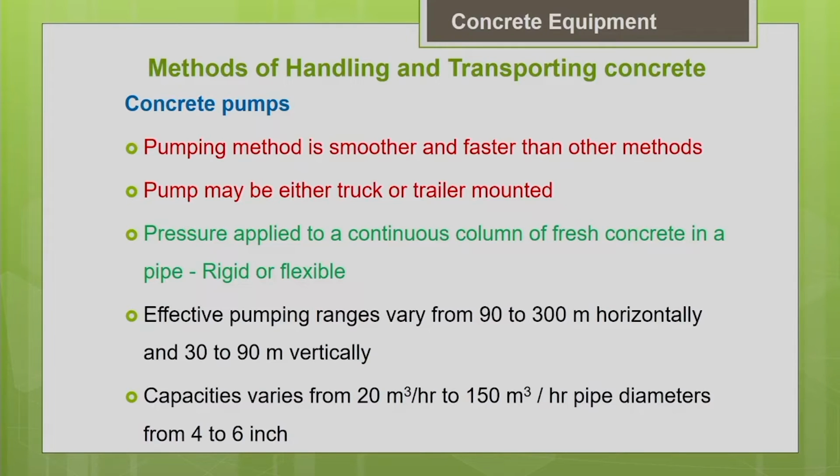So, the next method of transporting the concrete is concrete pumps. Okay, nowadays the pumping method is accepted as the best method of placement of concrete, because the main advantage with the concrete pump is you can avoid multiple handling of the concrete. Generally, when you prepare the concrete in one lot, you should place it in one lot. Thereby we can avoid multiple handling, that will avoid segregation of the concrete. With the help of a concrete pump, we are able to place it in one lot. So that facilitates the prevention of segregation of your concrete.